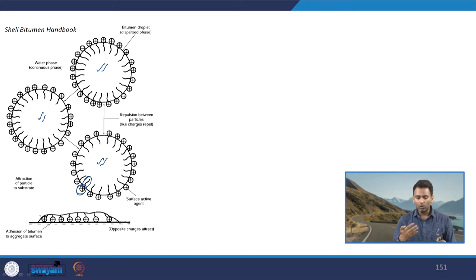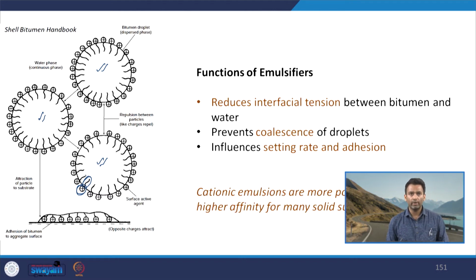And finally we will talk about how the bitumen emulsion is mixed with the aggregate and how bitumen from this system is able to coat the particles, because now bitumen is dispersed in globule form, but when it comes in contact with the aggregate particles, the aqueous medium will go away, only the bitumen which is dispersed will come close to each other and will coat the aggregate particles properly, so that we can produce a durable mix.